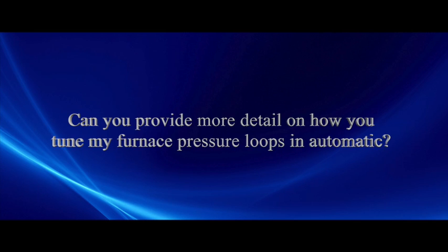Make a set point change, and look for any oscillation. If there is an oscillation and it's not decaying, you better decrease the gain right away. But if the oscillation is decaying, then you look at the period of that oscillation.